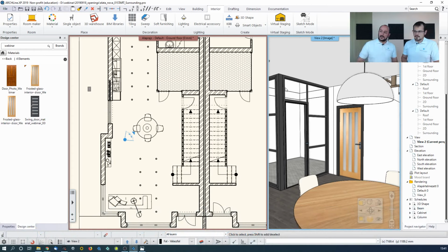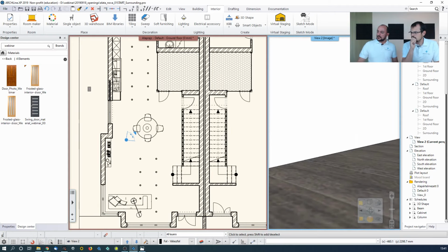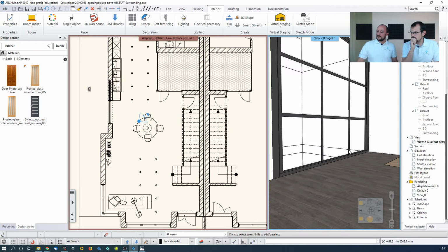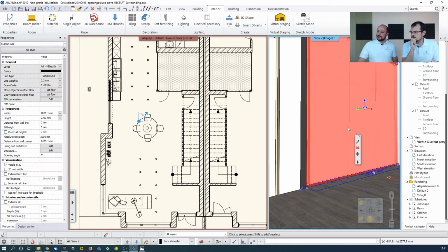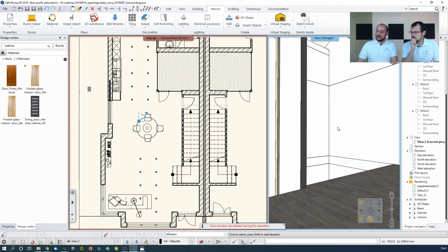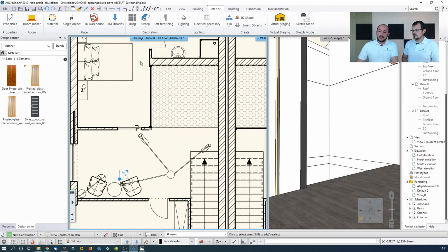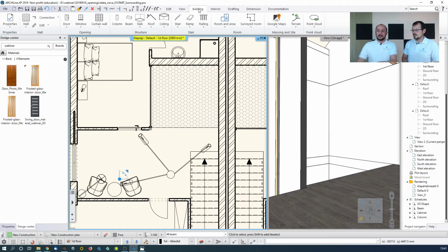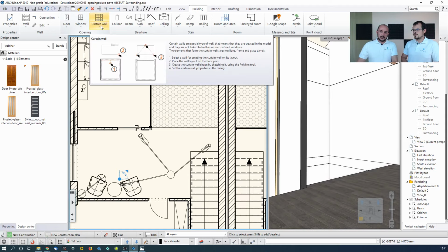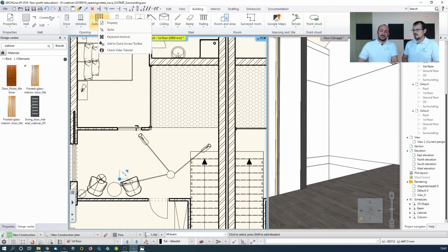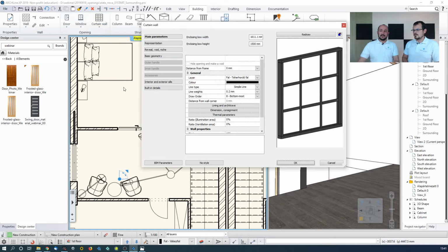How that goes, let me just go to the following floor, and for example remove this one and show you one feature of how it can be designed. One thing, again, it is in the building library and it is with the curtain wall settings. Now if you right click on any of those, you can predefine how this item will be generated, what will be the width, the height, and how all the rest of the settings will generate a structure like this.